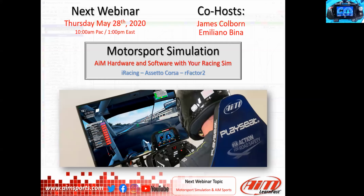You can take your AIM device, certain ones, if you go onto the website, you can see which ones are capable. It's pretty much mostly the current hardware, and you can actually have your dash in your iRacing rig or your sim racing rig, wire it up with a simple USB connection, and set the ECU protocol to it, just like you would with your gauge, and all of a sudden that gauge is working exactly like it would in your real race car out on the track. The shift lights are working, the predictive lap timing is working, all of the different settings, RPM, speeds, just like you're out on the track. So that is a very cool thing.